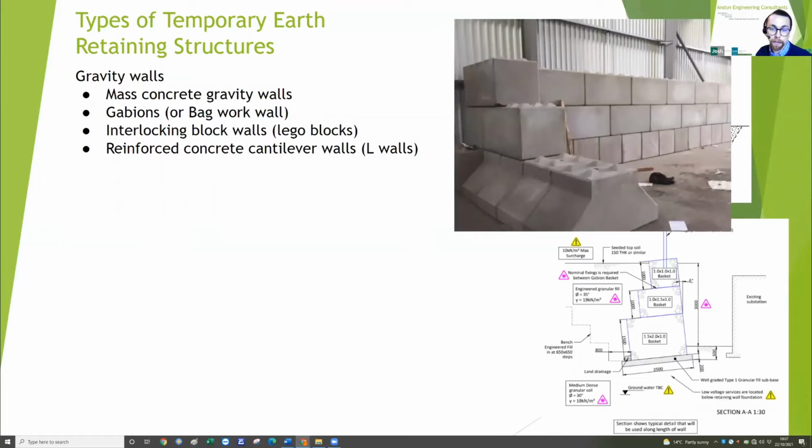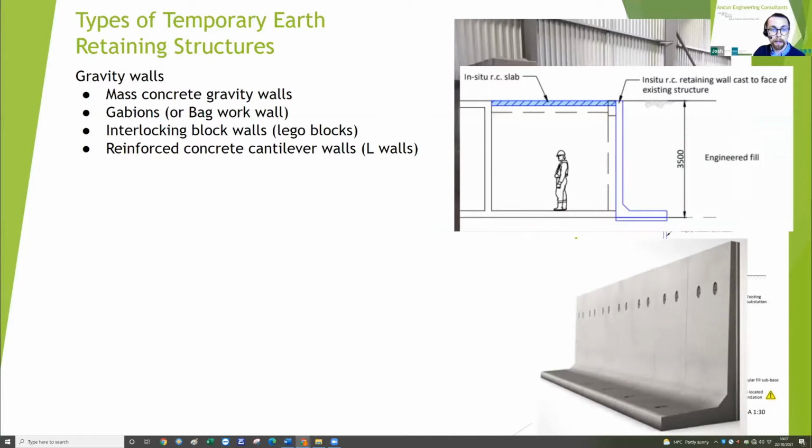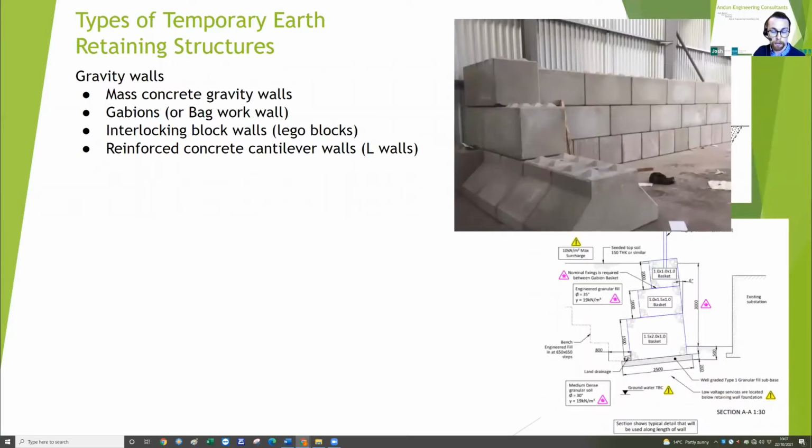A similar method to gabion basket is the Legato block wall. These are huge concrete blocks which are piled together, a bit like Lego blocks. They're precast, but you require some larger plant to move them around on site. They're essentially just similar to Lego block work, which I'm sure you all have hidden away at home.